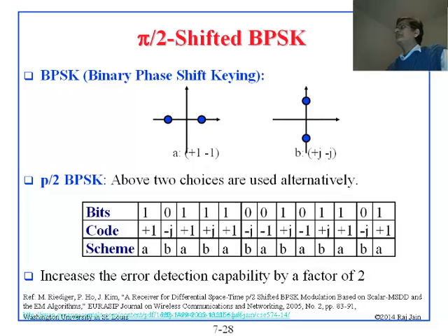Now, having said this, while the transmitter is doing BPSK, the receiver is really doing QPSK. The receiver actually has to know 4 phases. Right? So yes, you are getting the same effect as you would have gotten in QPSK. You could have sent 2 bits and then you could have had half rate. But here the sender is actually doing less work than with QPSK, I suppose. And so this is what is pi by 2 shifted BPSK, which is part of the standard in ECMA.